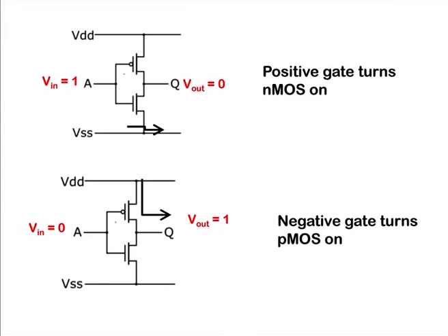In this one we have one PMOS and another one is the NMOS. Now, this CMOS will act as a NOT gate. If you apply a digital signal 1, some voltage, our output will be 0. If you apply 0 voltage, our output will be the maximum. So, we can use this CMOS for digital logic applications.